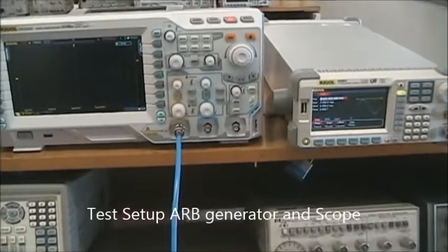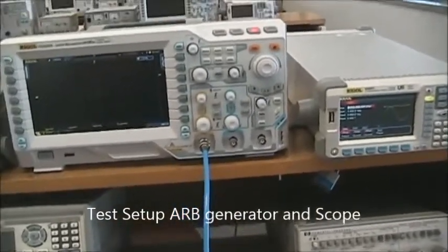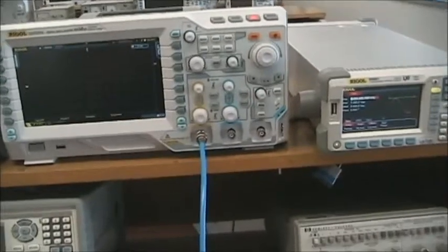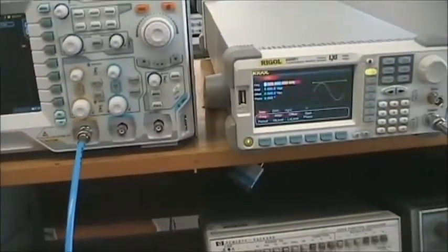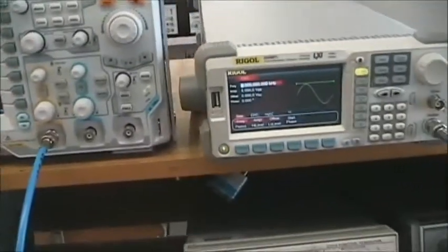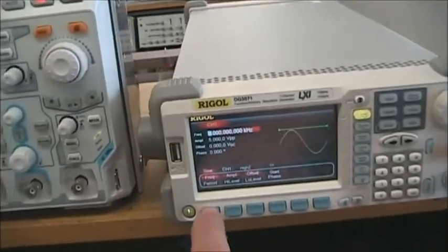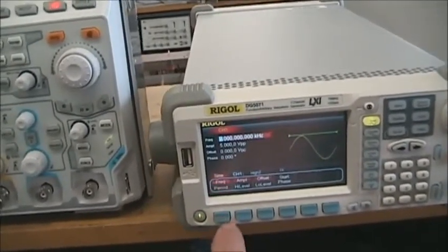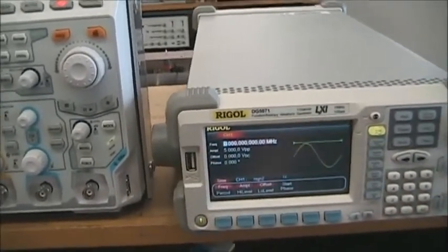This laboratory will start out where the last one left off on AM modulation. We will start with our AM modulator. When we turn on the scope and generator, we typically see a blank screen. We'll set the generator for 1 megahertz. So under frequency, 1 megahertz for our carrier.